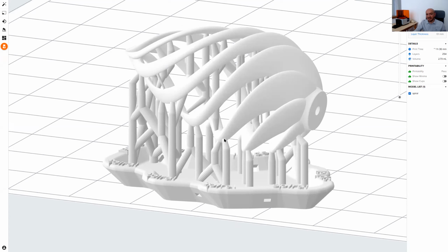The reason is that with such thinner parts, it will be easier to break with hand or with some mechanical equipment. If you have thicker parts here, then there will be a solid connection between the support structure and your part, and you may not be able to break it. So that's why people prefer such thinner parts at the connection points.